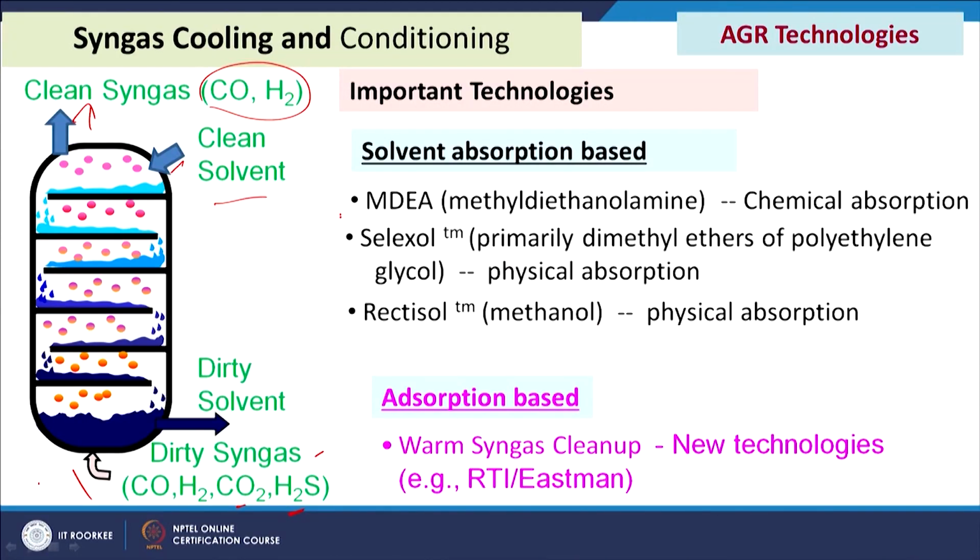So, MDA, we are having here chemical absorption. What is MDA? One solvent, that is methyl diethanolamine. Selexol is another solvent, that is primarily dimethyl ethers of polyethylene glycol, that is also physical absorption, and Rectisol, that is nothing but refrigerated methanol. So, that is also physical absorption.